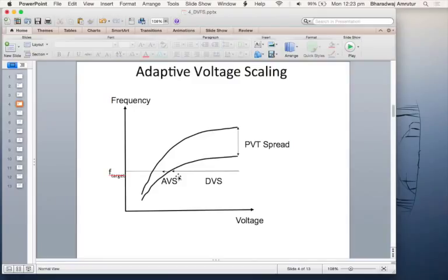But that is not the best way. Like, you are operating the faster chip at a slower frequency, so that is not the best possible. Correct. So the question being asked here is that if you use the conservative lower bound, then you're leaving performance on the table for the fast chips. Because out here, there is one chip or a very small number of chips which are determining this; they are the weak links, right? They are kind of holding hostage all the other chips in some sense. So I'm promising only say 2.4 gigahertz, whereas a lot of chips would be able to run much faster, and there will be a few outliers which will run even faster, right?